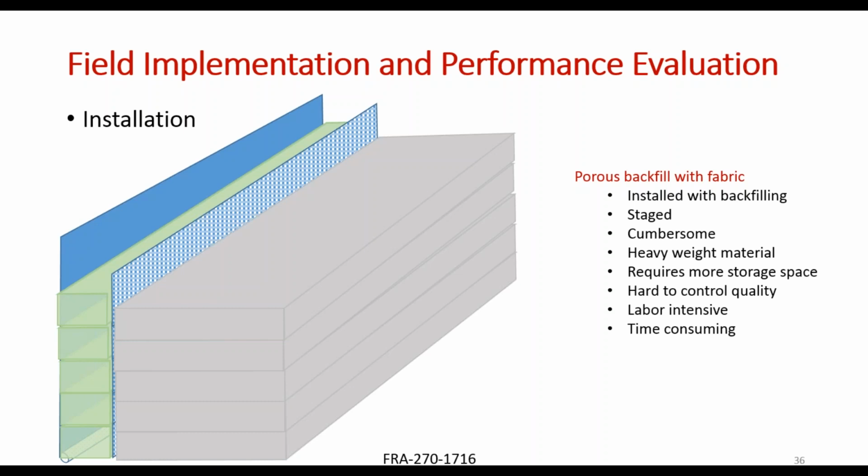And it's also labor intensive, because when you place that layer of porous backfill, typically we need hand shovels, okay, to make sure that it's about 2 feet away from the wall. And also it's time consuming because it's a staged and interchanging process.